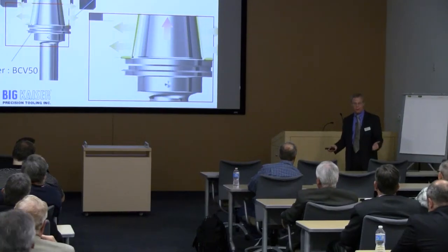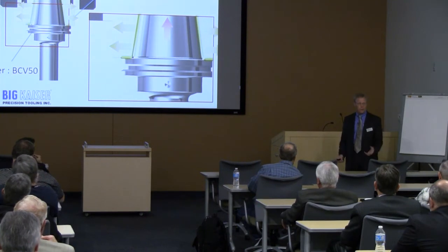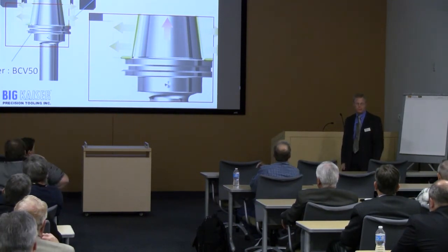We also sell tools that can automatically clean the spindle face if you're getting into a precision area. Or let's say you're going to use 3 tools Big Plus and the other 80 are standard Cat 50. Those precision fit tool holders you can clean first automatically before you put the tool contact in. Unlike HSK or Capto, everything's tool contact. So they all get a face contact all the time.